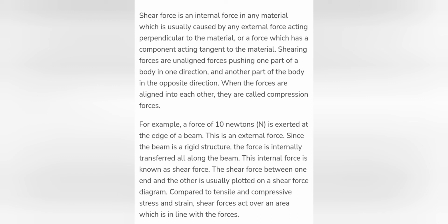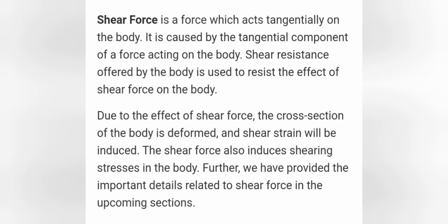Now let's see what kind of cracks are produced in a concrete beam due to flexure and shearing stresses. Let's assume a concrete beam loaded with line load W. There are basically three kinds of cracks produced in concrete, which are flexural cracks or cracks due to bending of the beam, flexural plus shear cracks which are caused due to combination of bending and shear forces, and lastly shear cracks which tend to come up near the support due to shear forces.